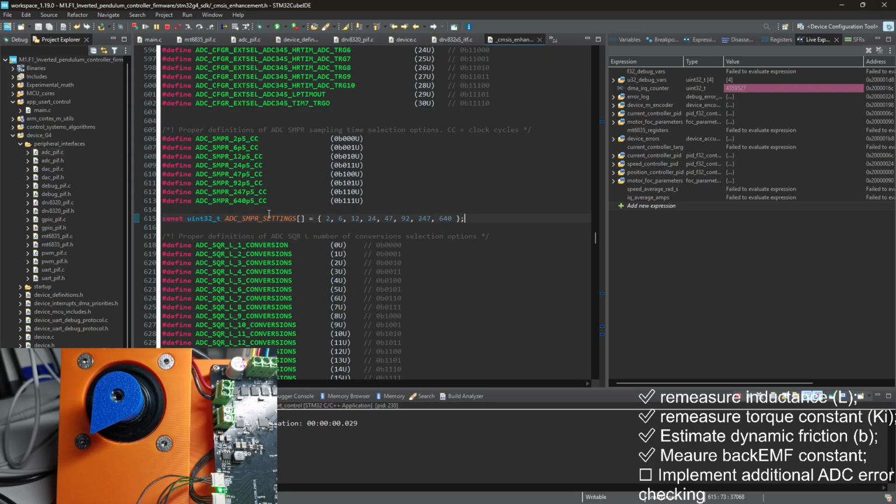No, it actually probably means that you have half time of transistors open and half time closed, and they all open and close at the same time. So actually it will be a free run. It will be just a free run where you have things both open to power supply and from power supply. And if you want an actual free run as it's supposed to be, you can just set it to 0 so that your low side transistors are always open. And in this case, you will get a proper free run without touching other pins.